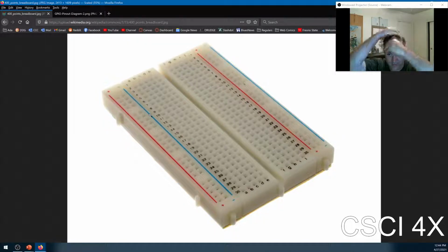Because the way the breadboard is lined up is that you can't see it. And so the first time you work with a breadboard, you need somebody kind of to explain it to you. But basically, all of these holes in a vertical column here are all electronically connected. There's a piece of copper underneath the breadboard that's running vertically like this. And so if I put the 5 volt pin attached to my Raspberry Pi plugged into any of these holes in the left column here, then all of the holes in the left column here are supplied with 5 volts.